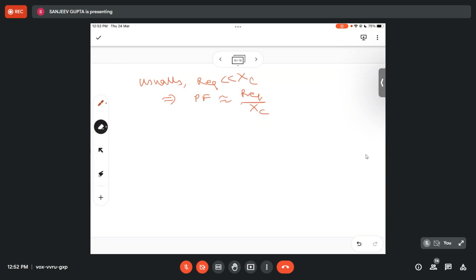Okay, so this R equivalent, what we have learned just now, is also called ESR. Some books write it like this. It is called the equivalent series resistance, but basically it includes both the resistances. So this is one parameter. For an ideal capacitor, R is a parasitic, so ideally power factor should be equal to 0, because R is a parasitic.